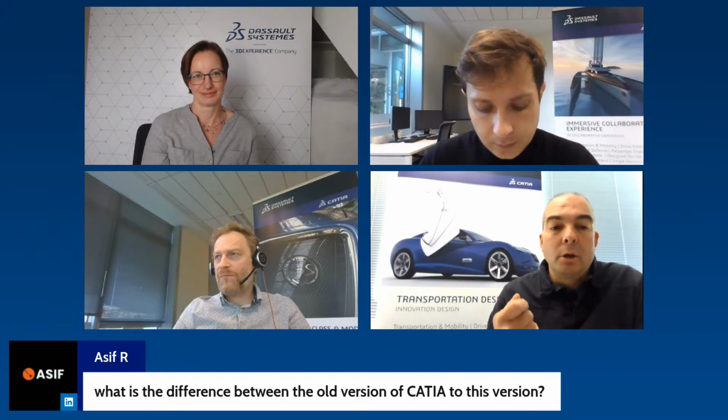This is really allowing you to do Class A with the mathematics of ICEM and the power of features of CATIA. But the user interface is really CATIA user-oriented. Really sequential, you need a lot of method to do it. So it's something we really position for accessories and niche parts, the finishing of the Class A.